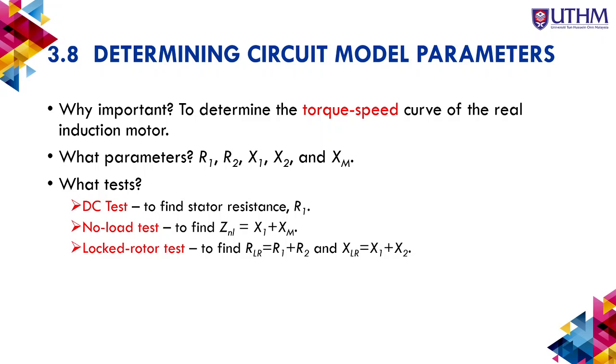These pieces of information may be found by performing a series of tests on the induction motor that are analogous to the short circuit and open circuit tests in a transformer. The tests must be performed under precisely controlled conditions, since the resistances vary with temperature and the rotor resistance also varies with rotor frequency. The exact details of how each induction motor test must be performed to achieve accurate results are described in IEEE Standard 112.